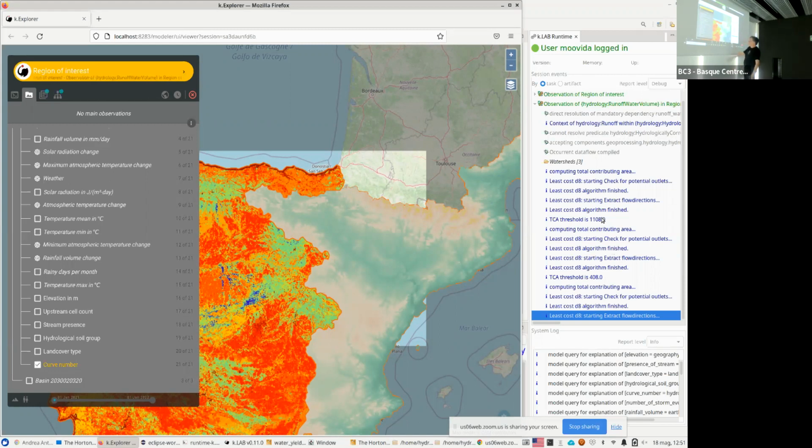So now it's still working because it is computing just the initialization values of those models for each watershed independently. And what you can see here is that it's taking the first initial data. So this is the elevation data with the elevation color map. This is the curve number. Yeah, exactly. Curve number, which is kind of nice to look at because it's very happily colored, but it's basically reflecting the runoff and infiltration potential, depending on vegetation, soil type, and this kind of stuff, etc.